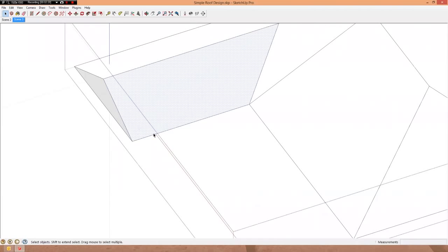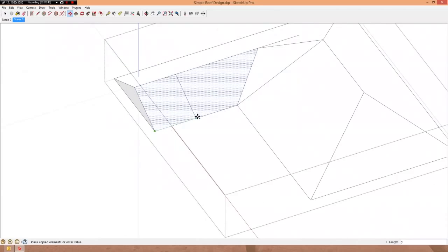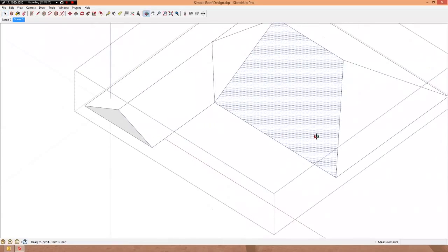this face is selected. I'm going to use the Move tool, with the shortcut key M. Hold down the Control key. See the plus sign on the lower right side of the cursor indicating we're in copy mode now. I'm going to copy this face and drag it along so that it's moving in this direction, and drop it right there. So I've used this to extend it. Now I have two faces. I'm going to delete this edge, so this is one face. I'm going to do the same with this one right over here.